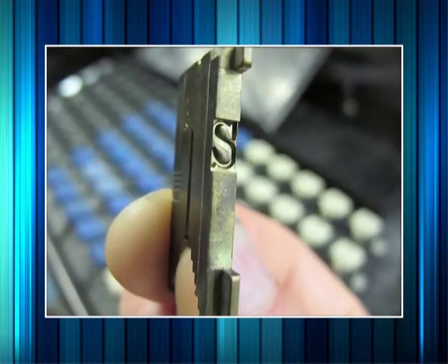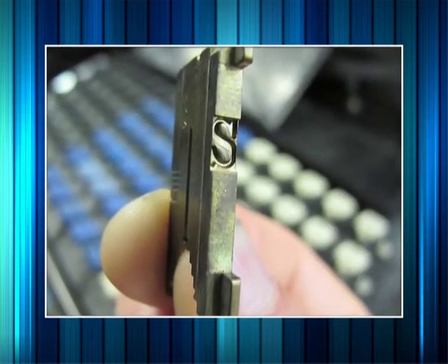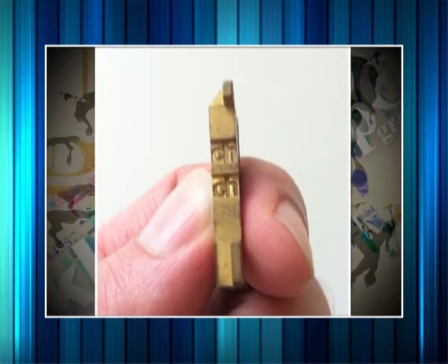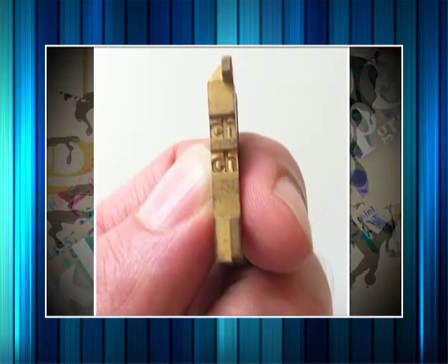They were lifted by these teeth to the distributor bar, which had grooves to correspond with the teeth on the matrices. The grooves on the distributor bar were designed so that when the matrix was above the correct channel in the magazine, there were no grooves to correspond with the teeth of the matrix. So it fell into the correct channel.